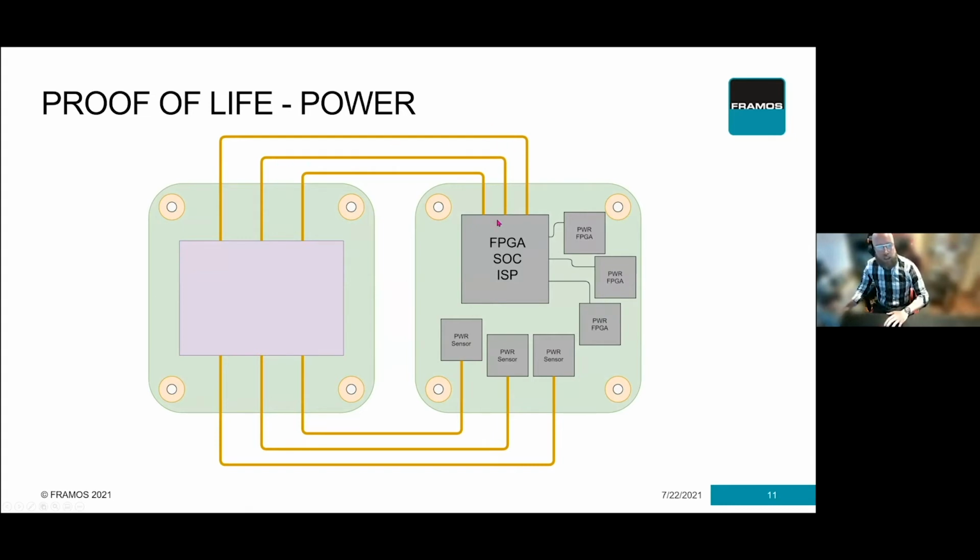Now, these 3 extra lines at the top here are also critical. These are representative pin strapping. When you turn on the power supply on these sensors, at a certain time you need to have a particular pin held high or low. If that pin is held correctly, then the system will communicate as you expect. Otherwise, you might be trying to look at high-speed data when you thought you had selected a low-speed data interface.